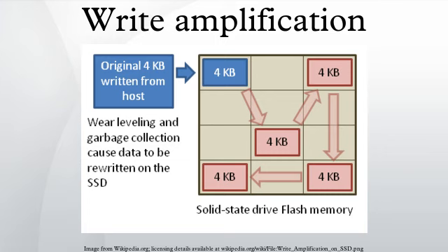Write amplification is an undesirable phenomenon associated with flash memory and solid-state drives where the actual amount of physical information written is a multiple of the logical amount intended to be written. Because flash memory must be erased before it can be rewritten, with much lower granularity of the erase operation when compared to the write operation, the process to perform these operations results in moving user data and metadata more than once. Thus, rewriting some data requires an already used portion of flash to be read, updated and written to a new location, together with initially erasing the new location if it was previously used at some point in time.